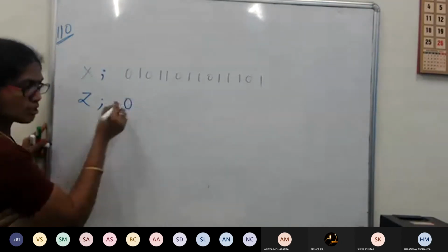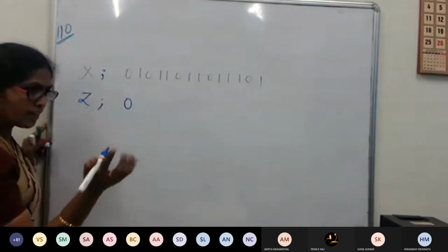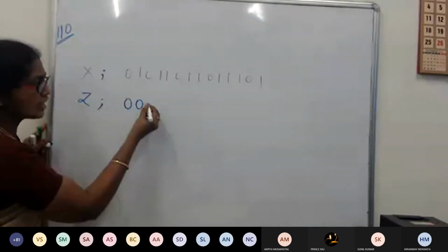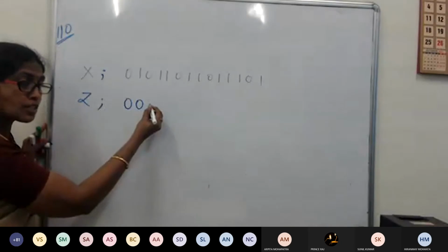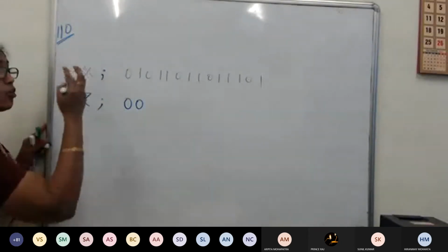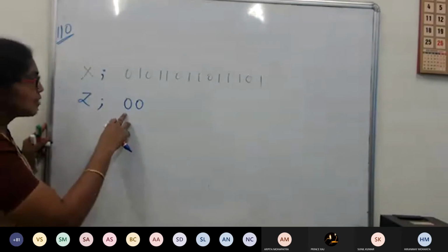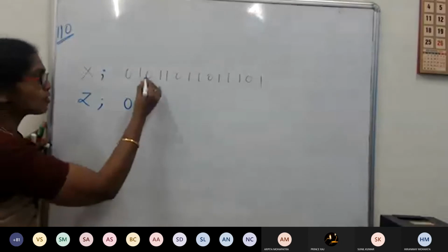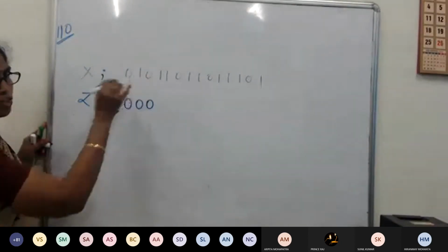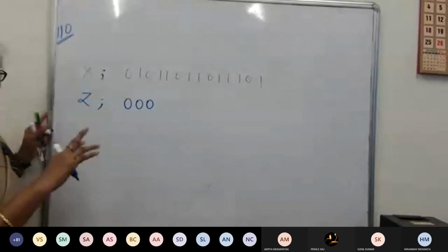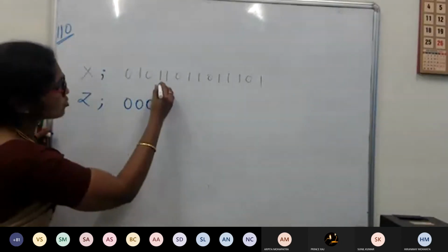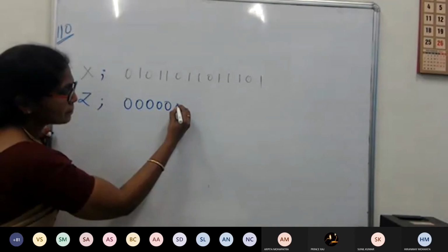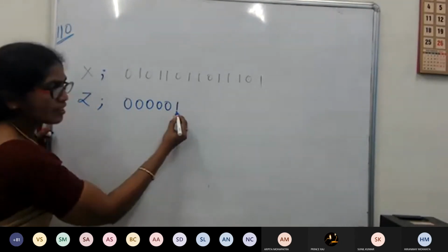So first bit enters, the sequence detector has no say, so it will give output 0. Then afterwards, same thing with the second bit, same thing with the third bit. The third bit is very crucial. Why? Because my sequence detector has to detect 110, which is 3 bits. Here the first two itself are not following the sequence. Since at the third bit also 010 is not our cup of tea, ours is 110. So next one, same thing. What about here? It should be 1, isn't it?